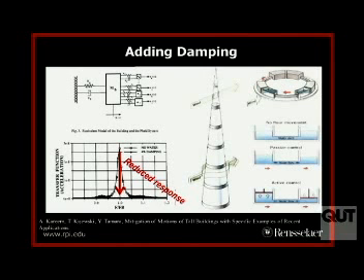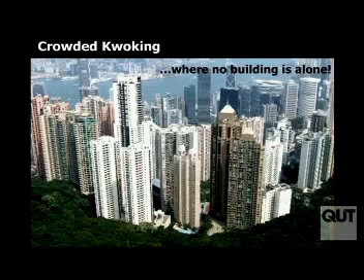And classic examples now include not only friction dampers but fluid dampers, tuned mass dampers, a whole range of dampers, which, again, there's lots of resources on the internet for that information. But all you're doing is extracting energy out of the flow. Instead of letting it go into the building, or you're letting it go into the building, but you're not letting it excite the structure, you're letting it excite the damper. And that'll improve the performance of the structure.